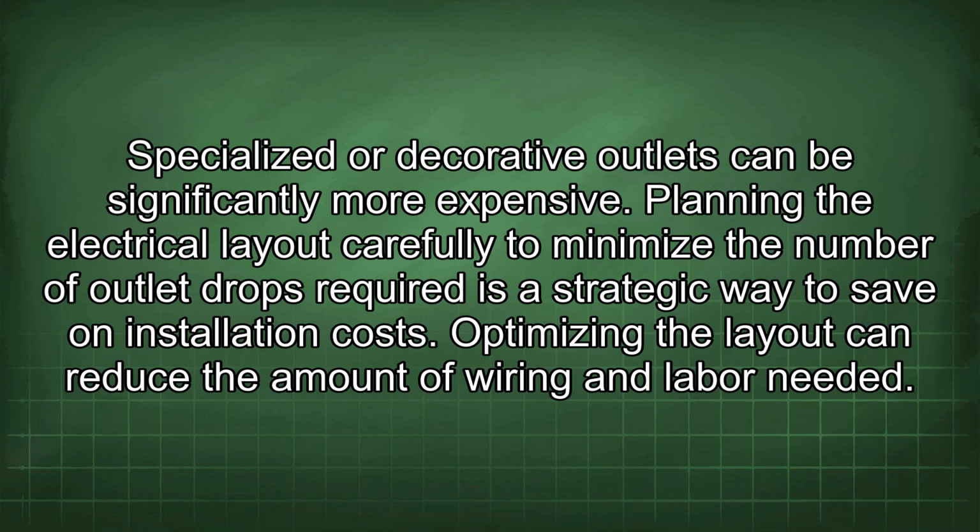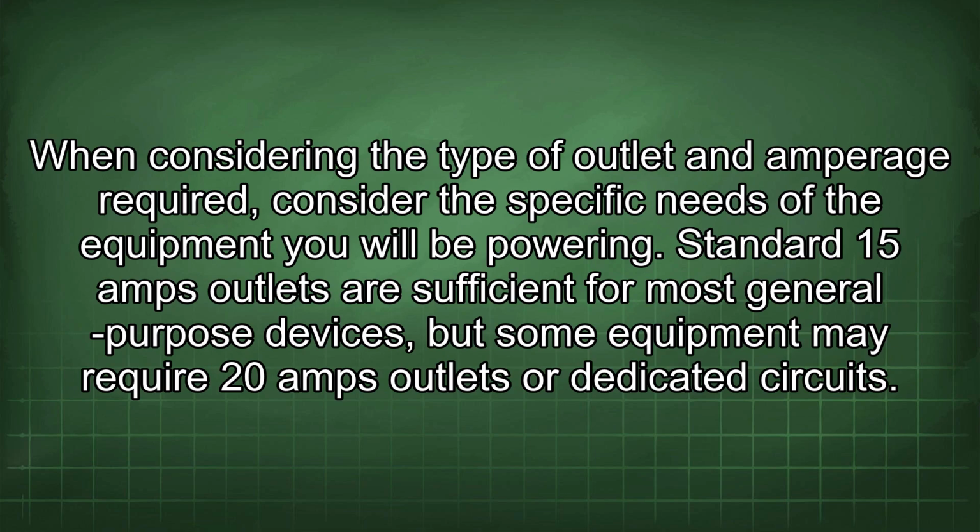Planning the electrical layout carefully to minimize the number of outlet drops required is a strategic way to save on installation costs. Optimizing the layout can reduce the amount of wiring and labor needed. When considering the type of outlet and amperage required, consider the specific needs of the equipment you will be powering. Standard 15 amps outlets are sufficient for most general-purpose devices, but some equipment may require 20 amps outlets or dedicated